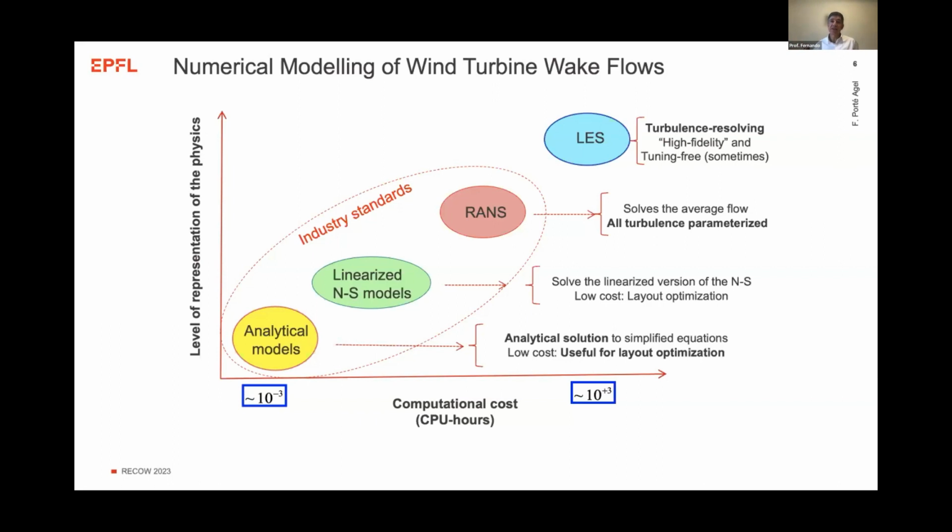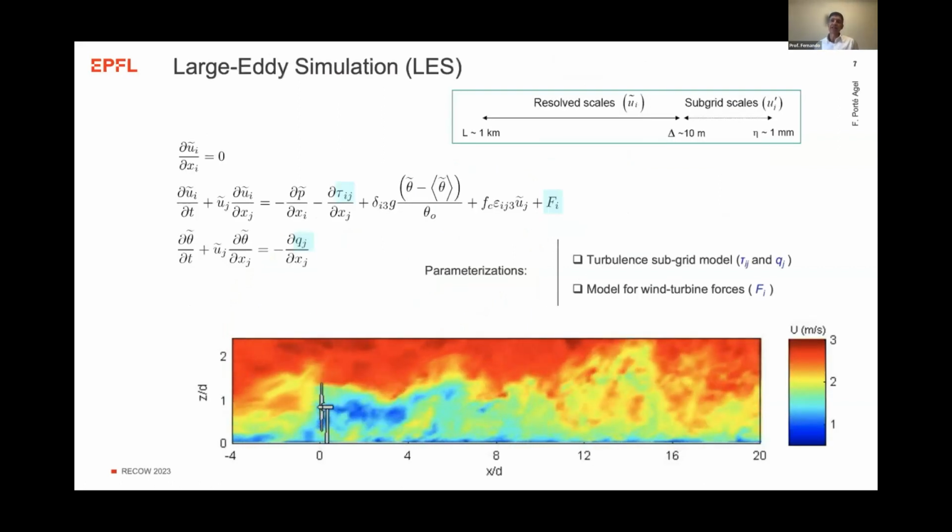On the other side of the spectrum, we have large eddy simulation. Large eddy simulation is a turbulence resolving technique. It's a computational fluid dynamics technique. So of course, in principle, it captures much more of the physics. It will be much higher fidelity. But of course, it also comes with a high computational cost, and I will be showing you some examples. Let's start with large eddy simulation.